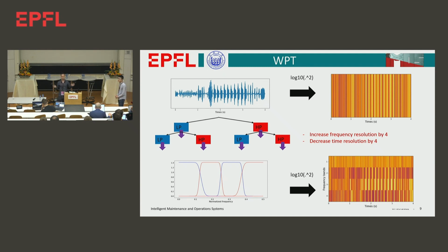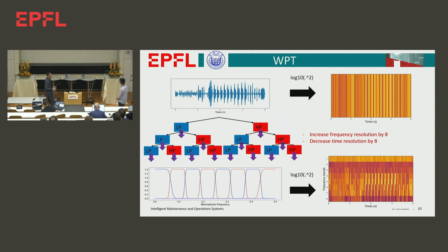So just a little remark: the subsampling operation is important, because if you don't put any subsampling operation, you do a low pass and then again a low pass and nothing particular happens. And if you do a low pass and then a high pass, you remove all the information in the signal. So the subsampling operation is here to diffuse the frequency information, to be able to, again, apply the low pass and the high pass. So, OK, and so we can continue like that.